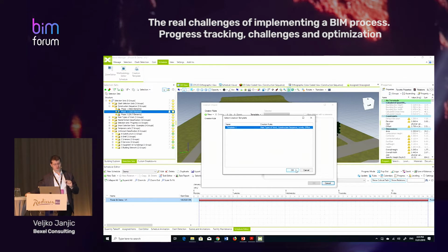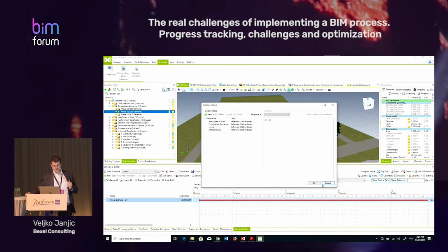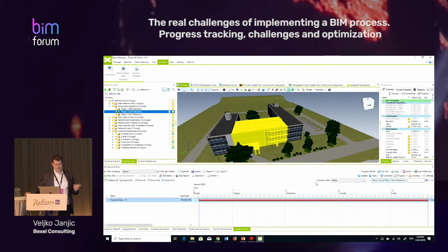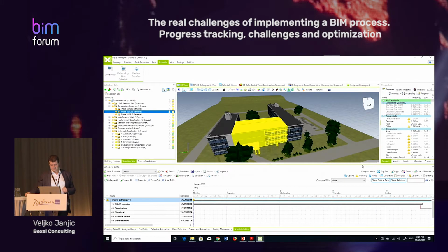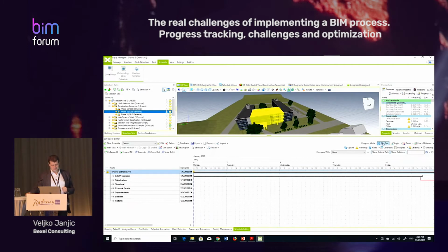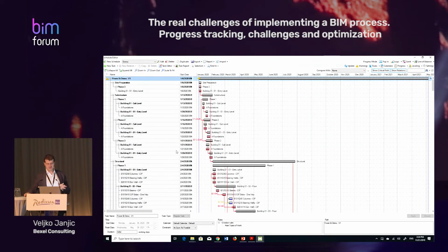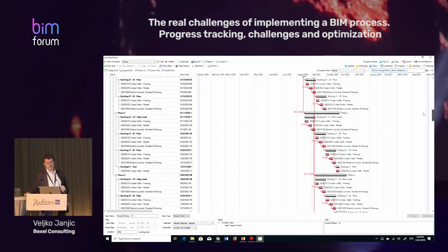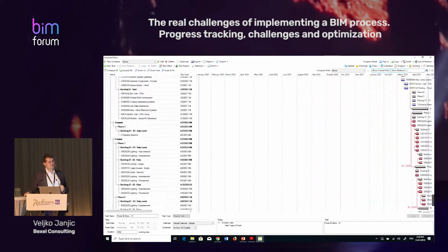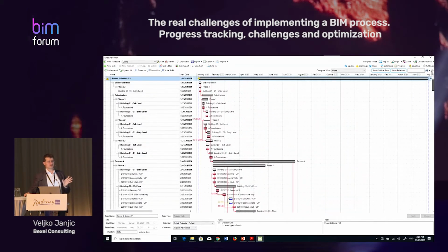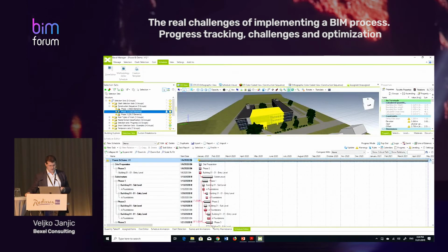Choose one methodology which has 4 levels: main types of work, construction sequence, building levels, and main methodology for office building. And say, okay. And now you see the entire schedule. Just to open it, just to fit it. Of course, you can later export. This is the entire schedule, with red being the critical path. All tasks are generated from the updated methodology.